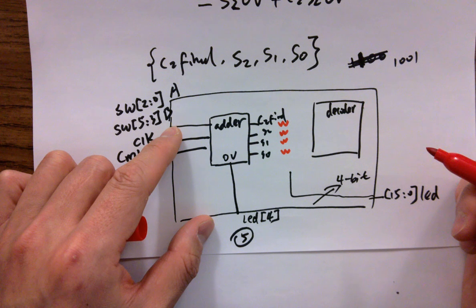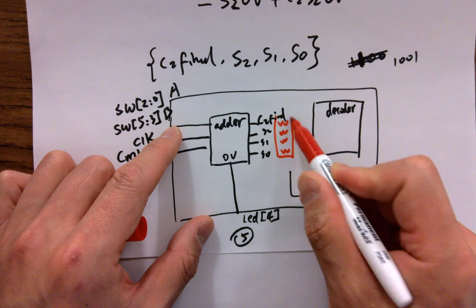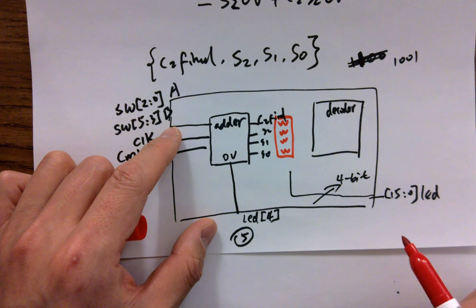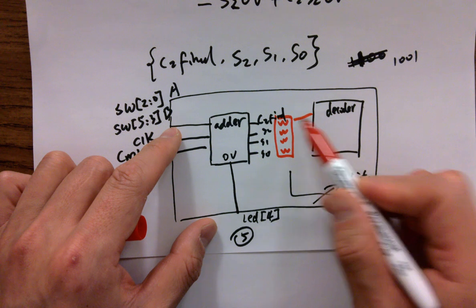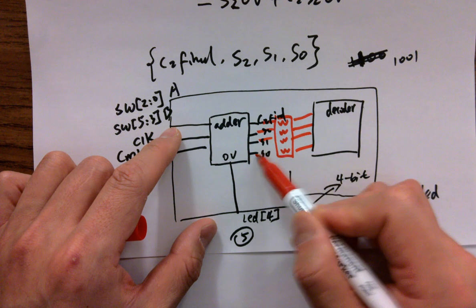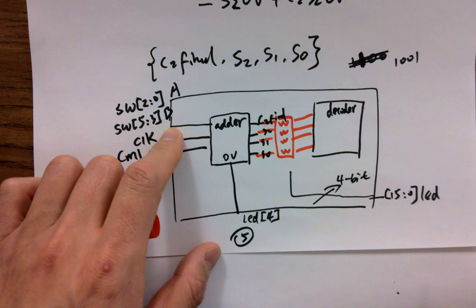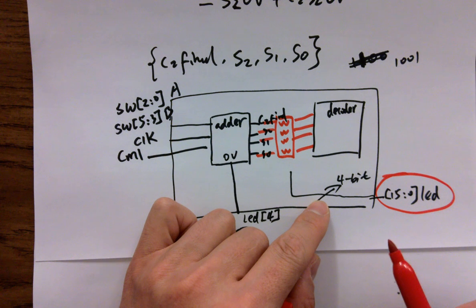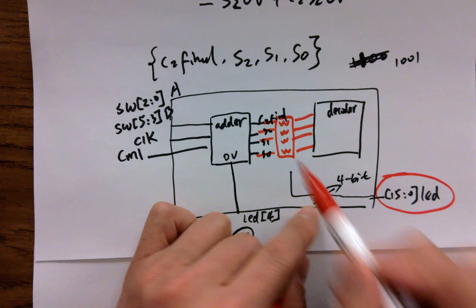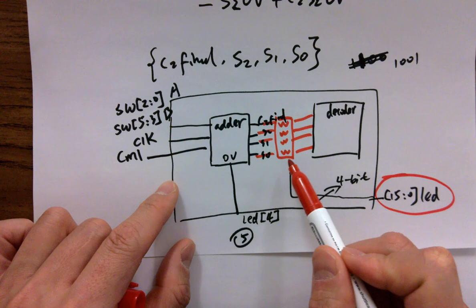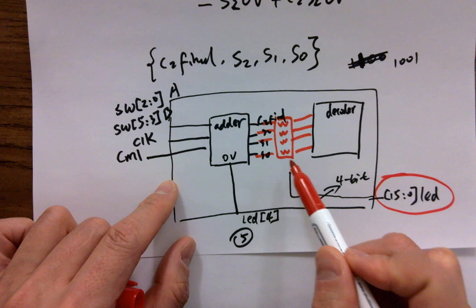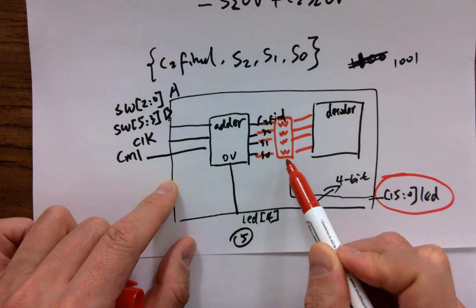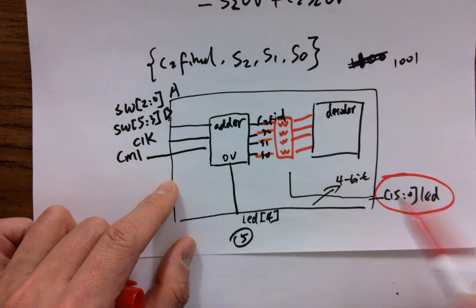Okay? Generate this 4-bit wire in your top. When you are doing the instantiation, the sub-modules are connecting to the wire, so they are indirectly connected to each other. And what about this one? LEDs are the top. Resources from the top. Can you still connect this one to the wire? Of course. In the top. So you declare this wire in the top. This belongs to the top. And eventually just directly assign these ones to LEDs. Very simple, just equal, right? Yeah.